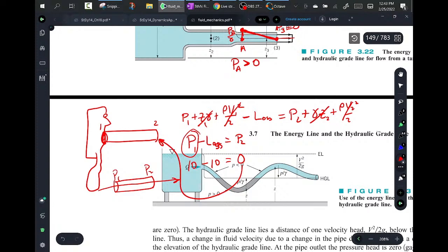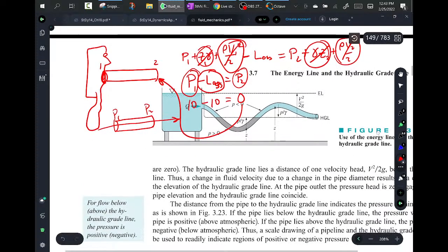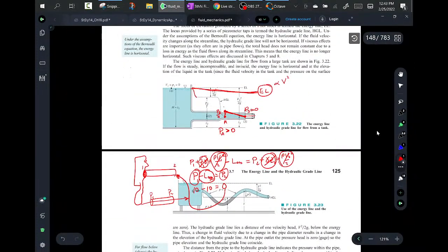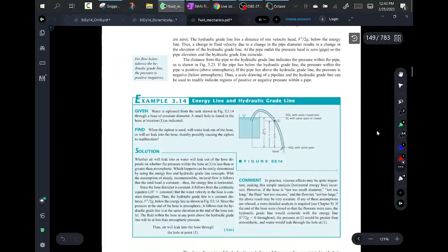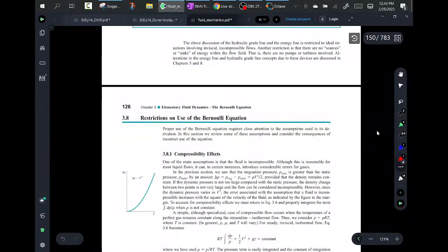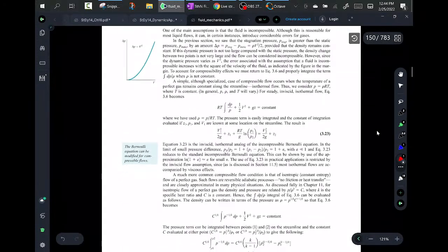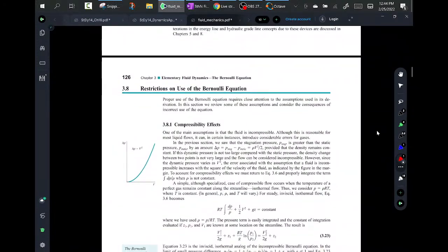So whatever the pressure is back here, you're going to lose every bit of it as you get to the exit. But you're not going to lose any velocity, you're not going to lose any elevation. So that's where the hydraulic grade line and the energy line come in; you'll see them drawn on drawings that most civils, professionally PEs, produce a lot of.